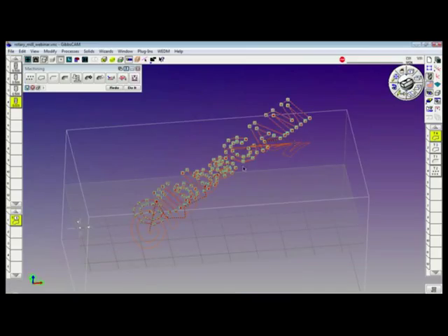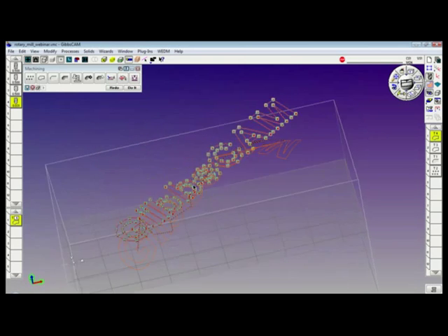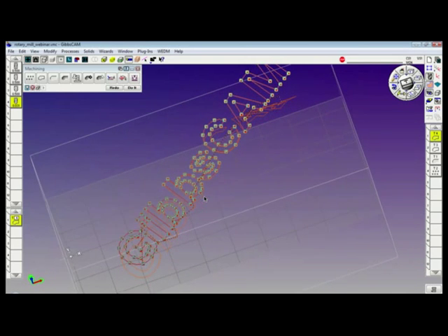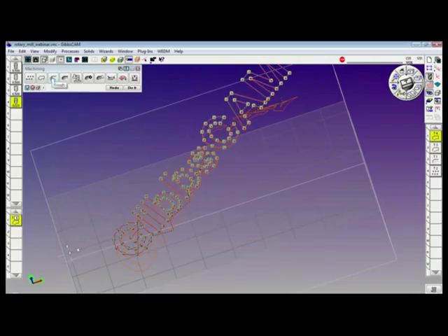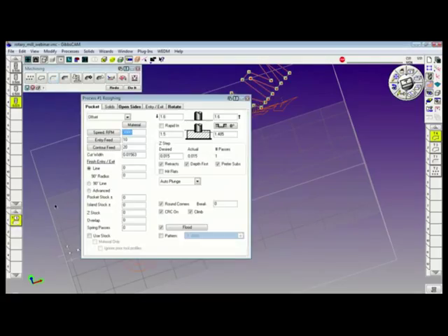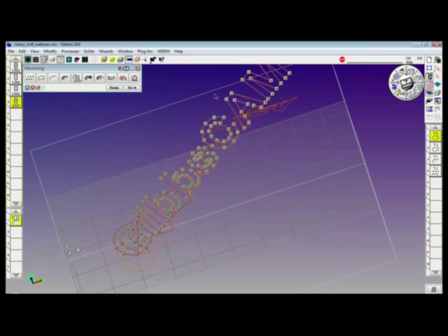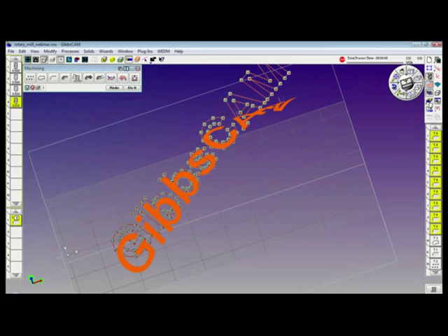Now that's a contour pass. It goes around the letters. If we wanted to do a pocketing operation, bring down the rough tile. Offset pocket. Everything looks good. Cut width, maybe 0.005. Get it nice and fine down there. Redo it. And there is our...